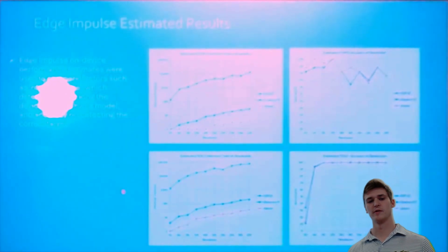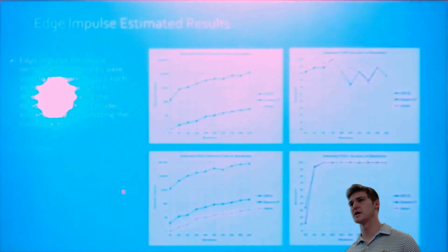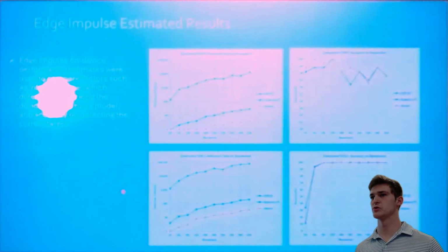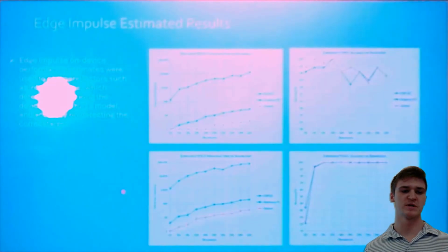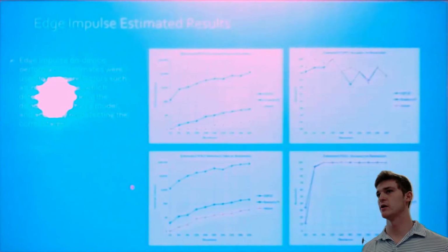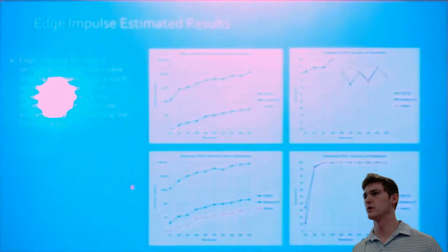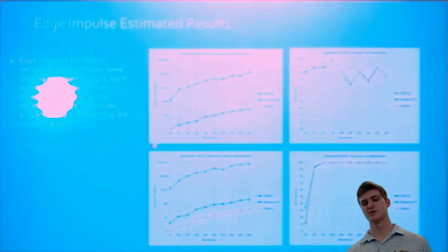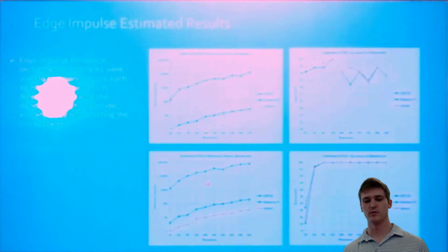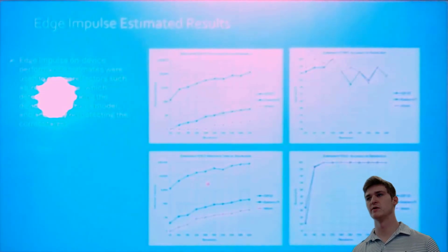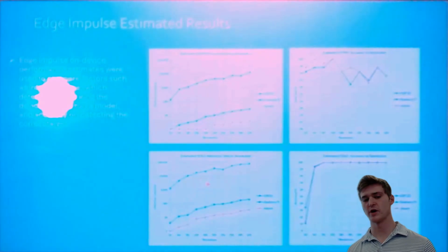That was my physical method for testing, but before I looked at those results, I did the estimated results with the Edge Impulse on-device performance estimates. I did that for both accuracy and inference time for FOMO and YOLO models on the resolutions from 32 to 320. You can see for inference time, the general trend is that with increasing resolution, the inference times are increasing for each device.